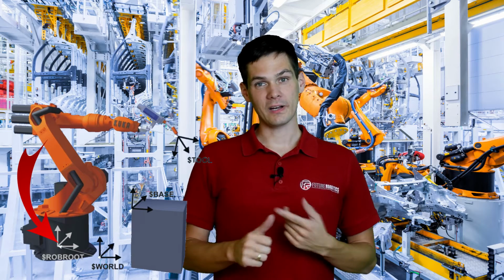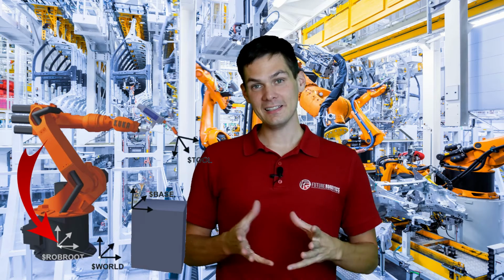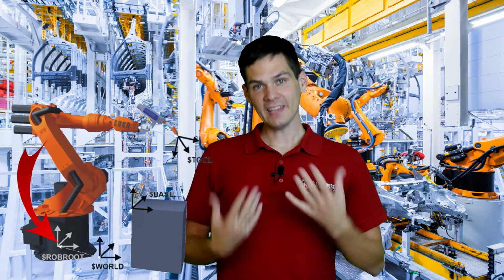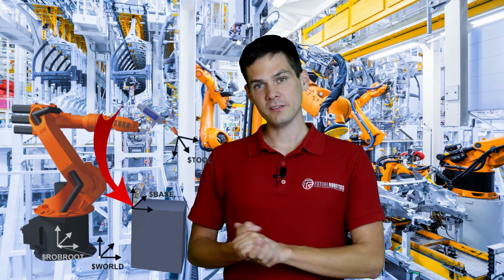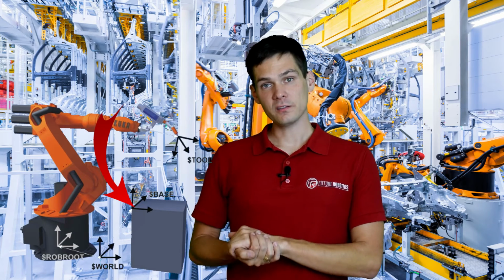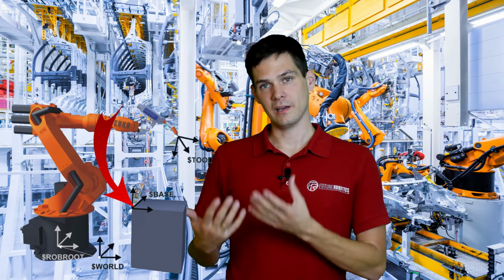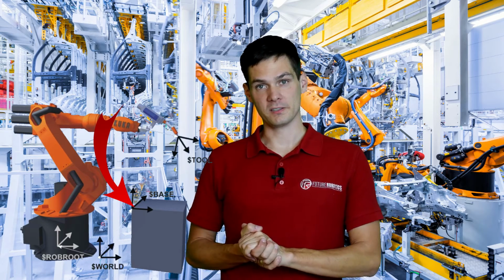So you can remember that the robot root, world coordinate system and base 0 are located in the same spot. Now in order to move that base you need to teach it, and we're going to do that in the exercises. You're shifting the base frame from the robot base onto another place.